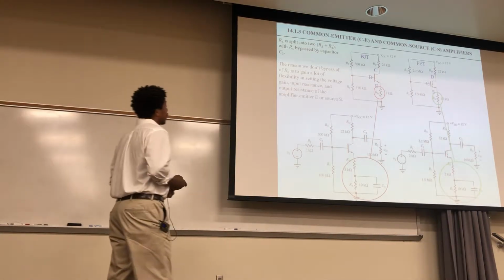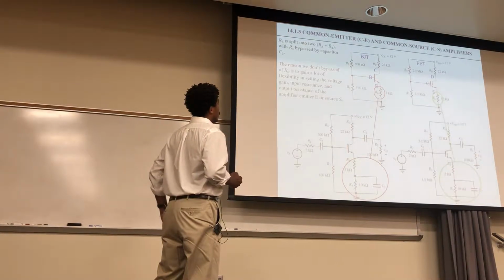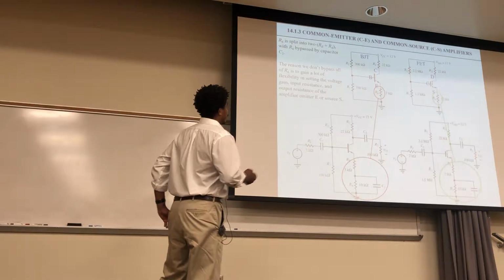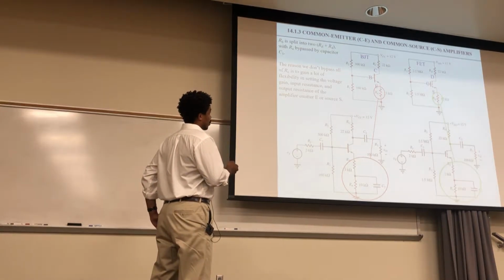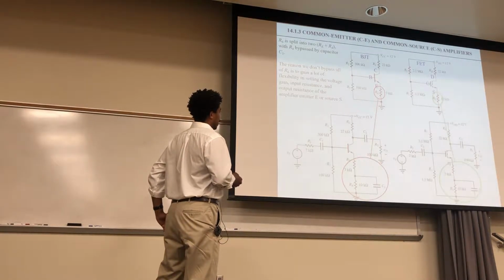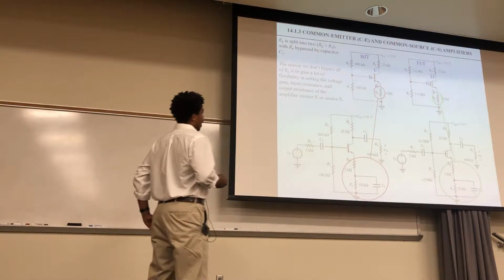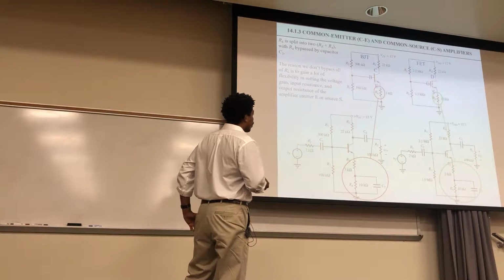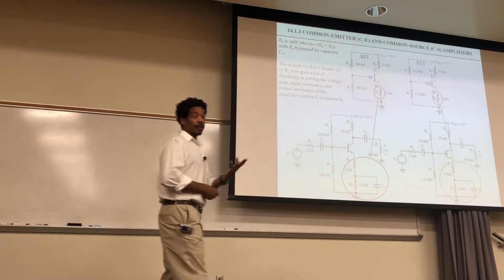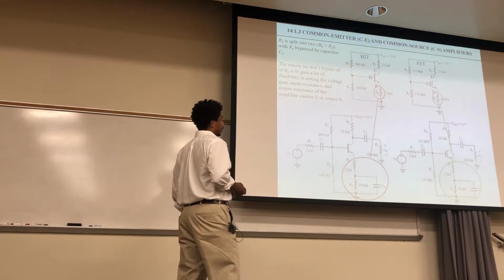Okay, so let's look at the common emitter and common source amplifiers. Okay, so we saw this expressed like this, right? So what we'll do is we'll take this resistor R6 and we'll split it in 2. So here's RE and R4. Okay, so that's what this resistor is being broken up into. And this R4 is going to be put in parallel with this capacitor right here, which we know by now is a bypass capacitor, and it's really important for controlling things.